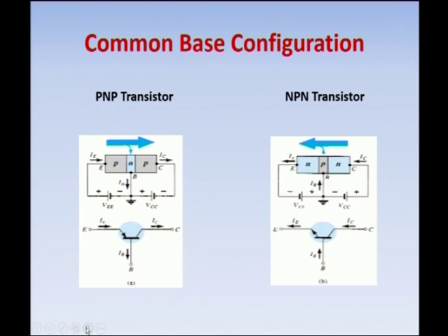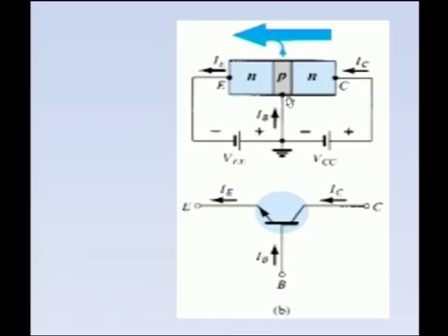What is the difference here? So, you have to give N, P, N in the rectangular box first. So, this N gives you the emitter terminal, and this P is the base terminal, and the final N gives you the collector terminal. The arrow mark is always different when you look at the PNP as well as the NPN. So, here in the symbol the arrow is away from the bar, it represents the emitter terminal.